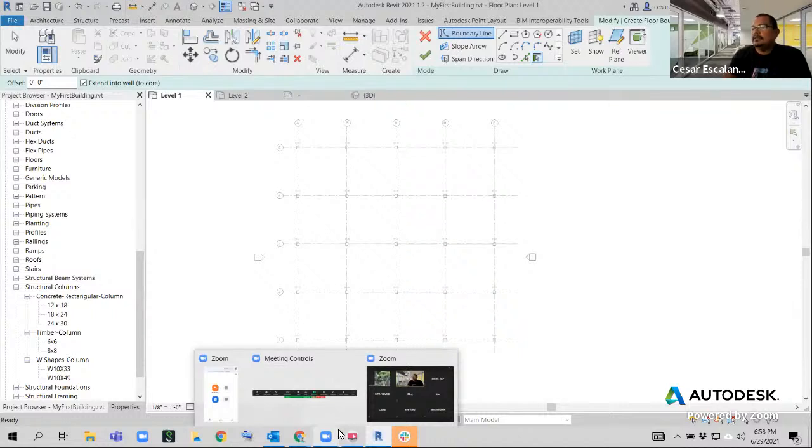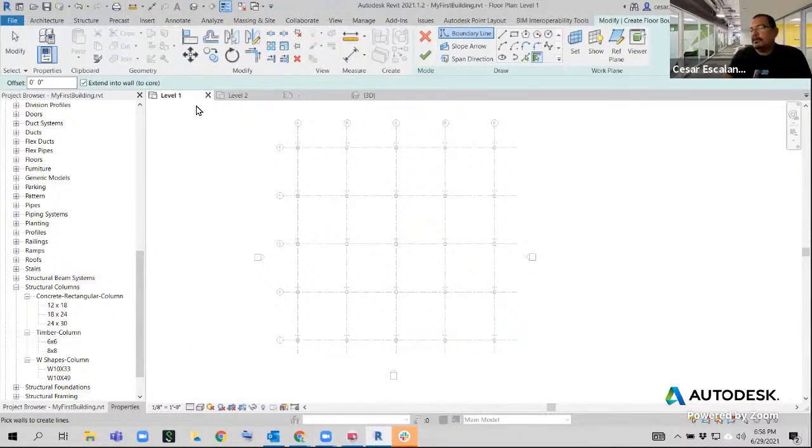All right, this is something new to you guys, for those who are new. When we create certain system families, Revit presents me with something called sketch mode. A sketch mode is a temporary display of working lines that define the boundary of system families. When you're in sketch mode, first, you can only create sketch lines.